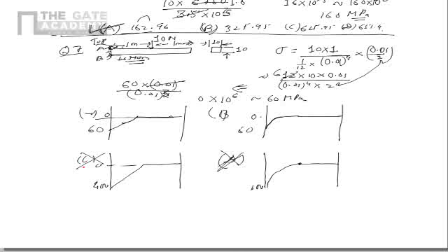So because it's a linear variation of x, let's say if I draw the shear bending moment diagram for this section, it will be px. So it's a linear variation. So M is proportional to px and sigma is proportional to M, right, which is proportional to px. So it has to be this way, like a linear variation. So this is wrong and this is right.